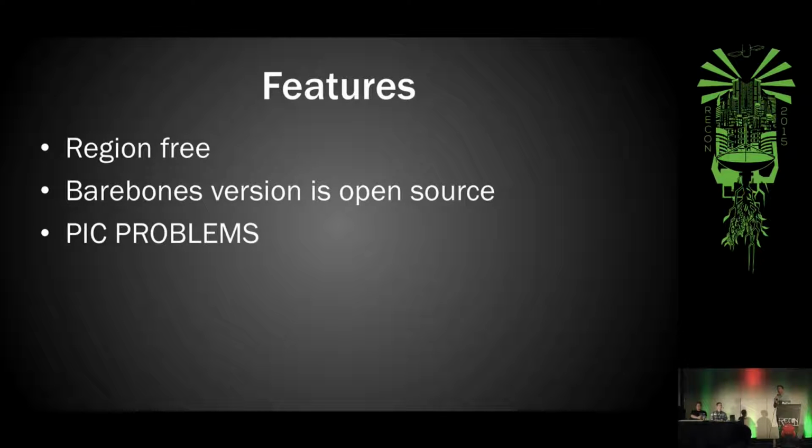But for this particular microarchitecture, it had some nice features that made implementing this stuff easier than it could have been otherwise. Remember, we mentioned that this is a 4-bit microcontroller. So when you've got things like carry, it all depends not on carry in the 8th bit, it's carry in the 4th bit. PIC actually has a feature called decimal carry. So if the 4th bit carries, there's a flag in the status register. So we were able to implement the code in a pretty straightforward manner, not having to think too hard about 4-bit math versus 8-bit math.